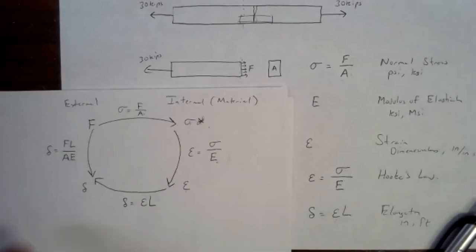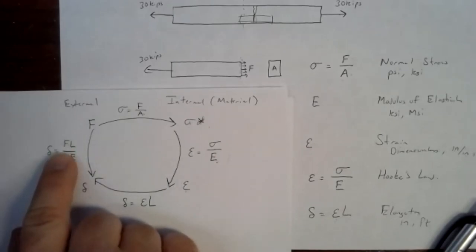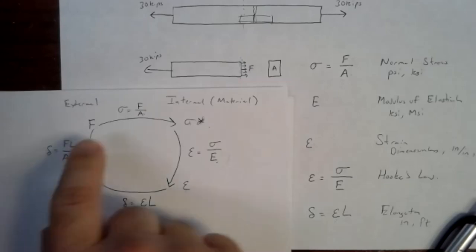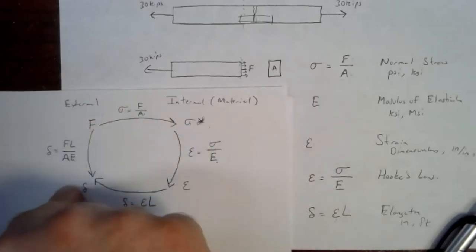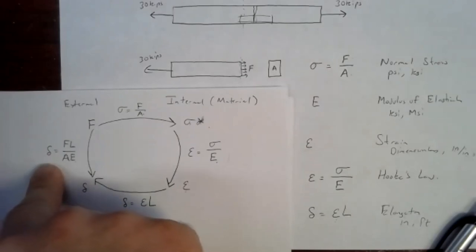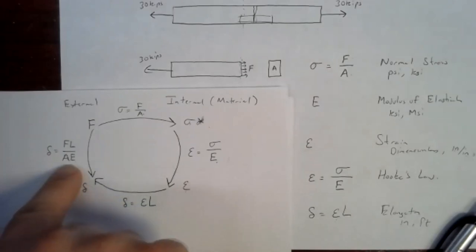If you've figured out the load on this beam and you want to make sure, well, I want to make it out of 2 inches by 2 inches aluminum. Figure out the stress first, make sure that stress is safe. Then you can go and plug it all in and make sure the elongation is good. Maybe the elongation you get's too much. So you need to lower the stresses by either increasing the area or maybe shortening the beam if you can, or going with a different material.